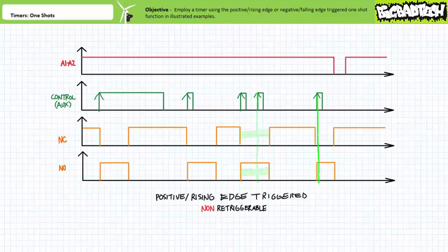The one tricky part of this timing diagram is experienced here when the timer experiences a loss of external power during an ongoing OneShot. Ordinarily, the contacts associated with the OneShot would assume their opposite activated state for a period of 5 seconds when triggered. The loss of the external power is kind of like a reset signal in that when the timer loses external power, the associated contacts instantly return to their deactivated state, thus overriding or resetting the ongoing OneShot.